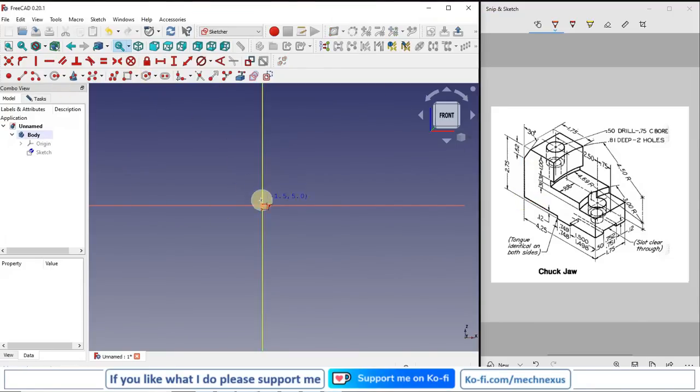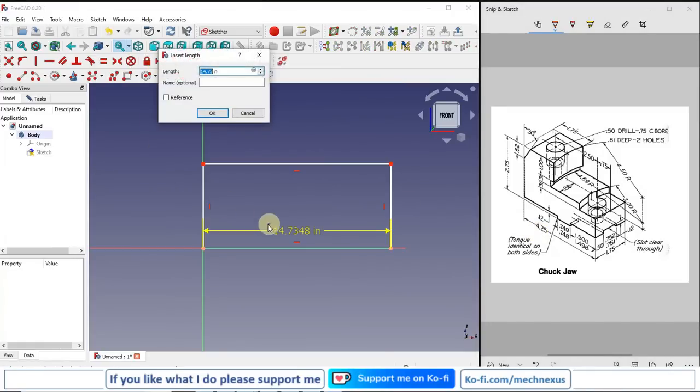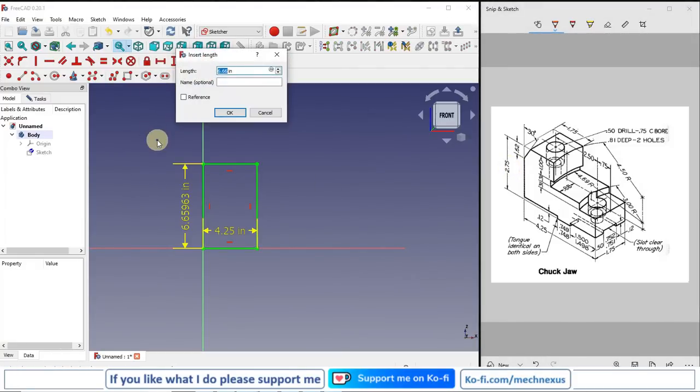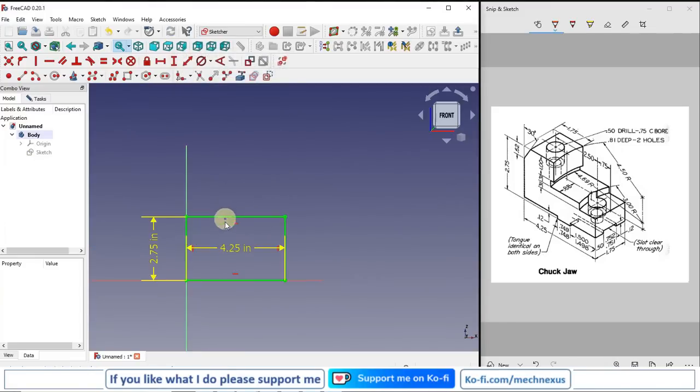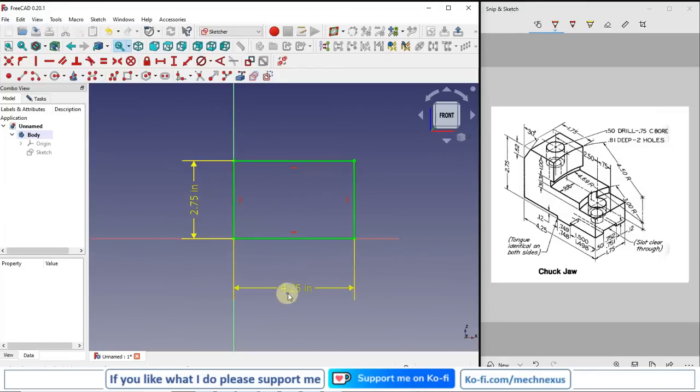So we will simply draw a rectangle here, and then we will give it an overall dimension of 4.25 inch. So I will give 4.25 and vertical height of 2.75. So I will select here and I will give 2.75. Now you can see that we see the inch here, so our unit has been set properly.